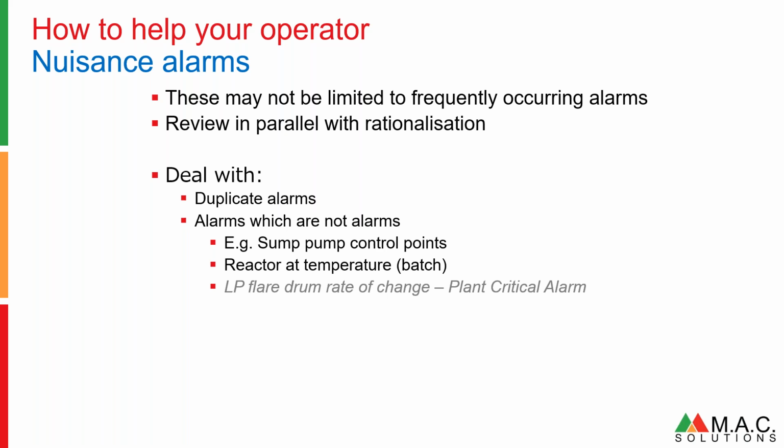Every day this alarm went off because it was an averaged calculation. The averaged calculation said, okay, between 5 and 10, that's 5. That's great. Between 10 and 15, that's 5. When it got to the end, the counter had to be reset from, let's say, 10,000 to 0. All of a sudden, we have a minus 10,000. We have a difference of 10,000. The plant critical alarm occurred. It happened every day because of this averaging calculation.